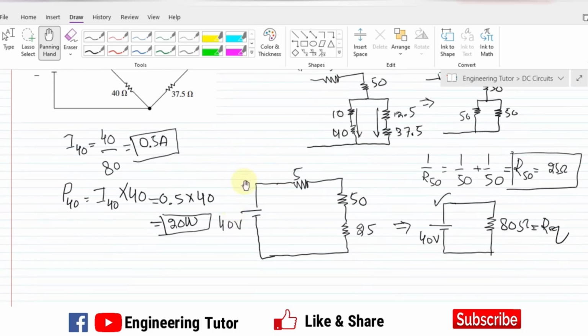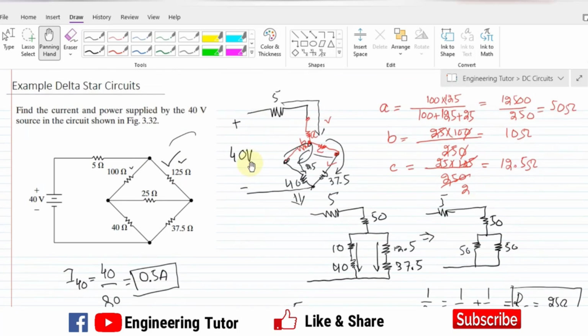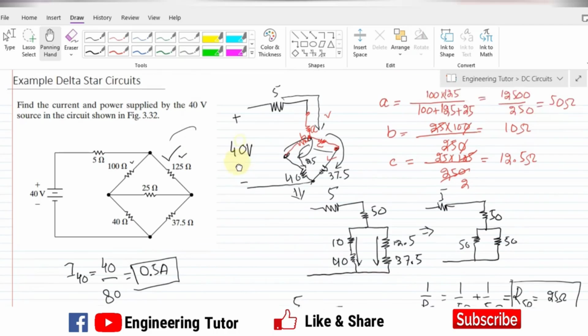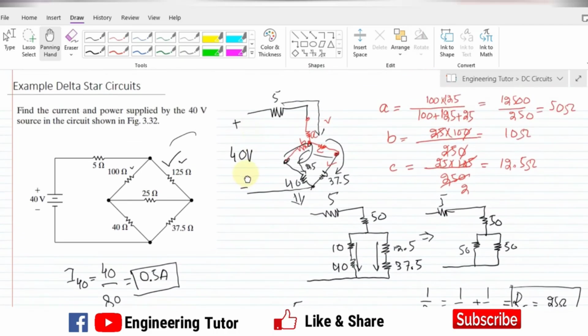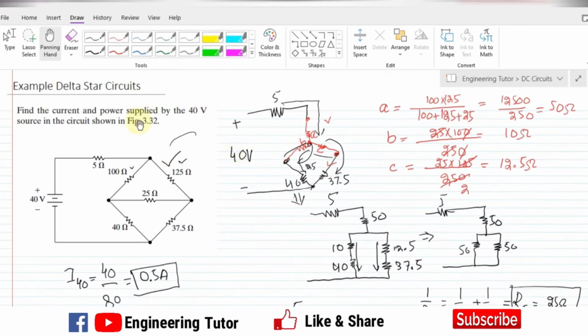Initially we have to find the equivalent resistance: pick any one of the two deltas, or any of the stars, and convert it into the other configuration. Here we have used the conventional circuit laws to find the equivalent resistance, and after that we find the current and power supplied by the 40-volt source.